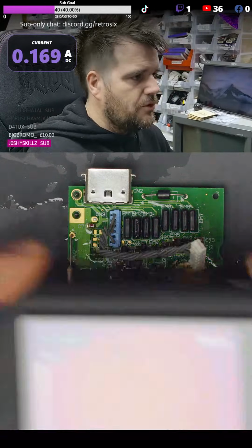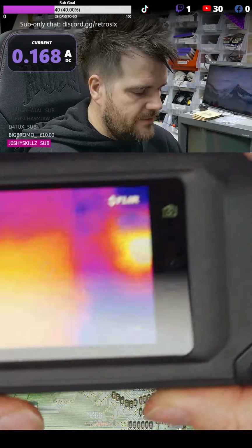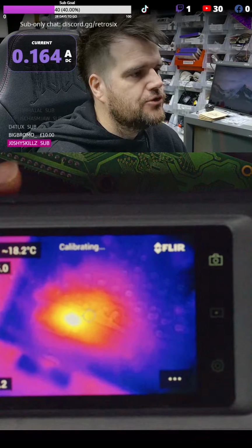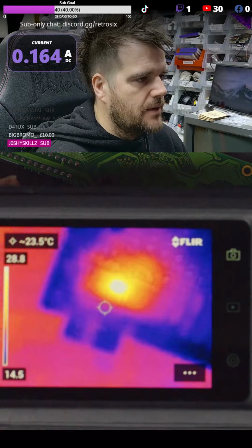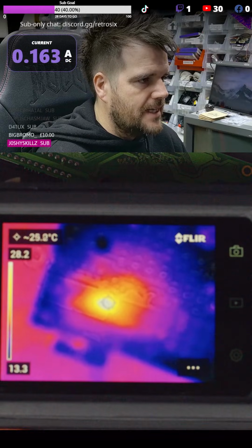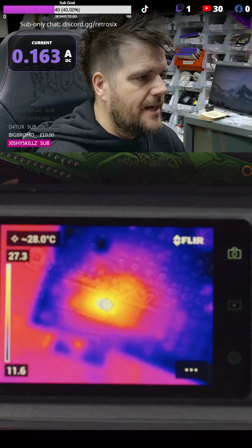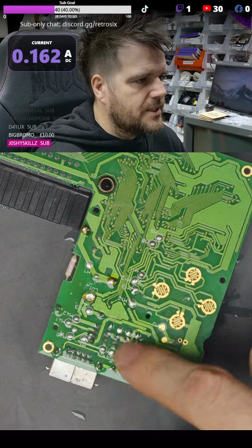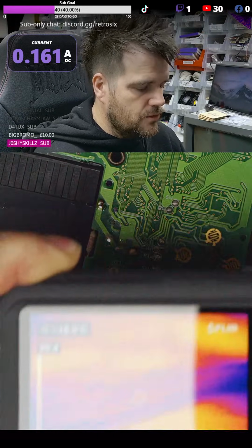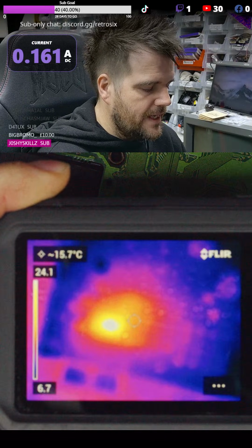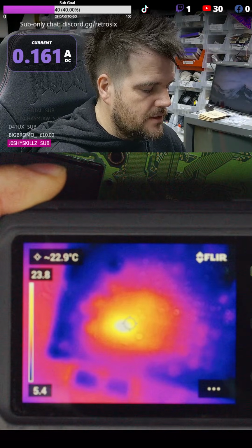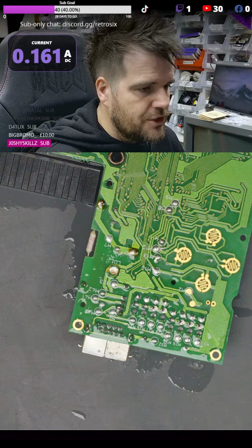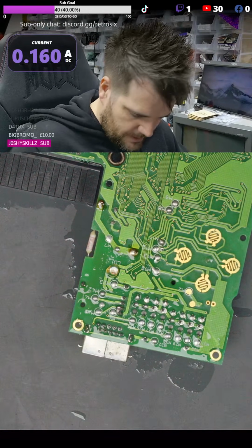So now we have the thermal camera up. You can see it's on. Let's quickly see if it's even going to detect that resistor, which should be getting toasty. Yeah, so straight away, there we go. So that's detecting that, and again, notice it's only 28 degrees. It's not super hot, but it stands out that it's not right against the board, basically. So it's a very clear hint that there's a problem, even though the rest of the board is fairly normal temperature. So this method works.